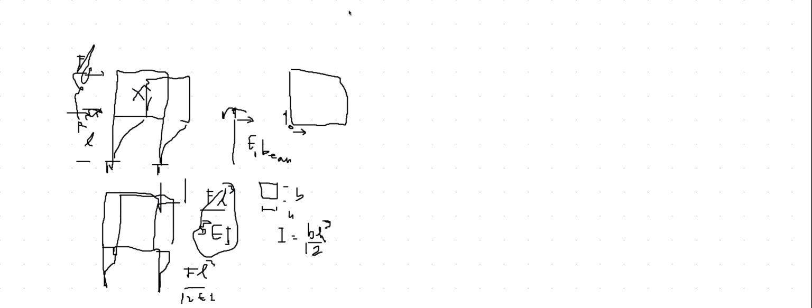Basically, the solution to that is having membrane elements which have the drilling rotation. That means a third degree of freedom that can take into account this rotation and kind of merge those things together and produce a deformation which is more of this kind. Okay, so let me maybe pause here.